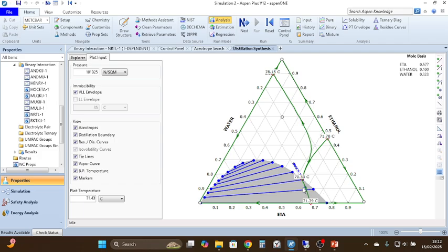Over here, you can perform some extraction and reach this point. And from this point, you can again move to this point over here to perform distillation again. So this is how we usually traverse a ternary diagram, or this is what a ternary diagram signifies: in order to reach from here to here, you just cannot cross from here, but you have to come through this path like this, which involves an extraction.